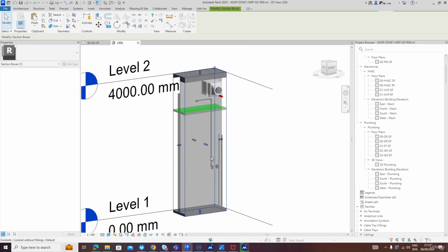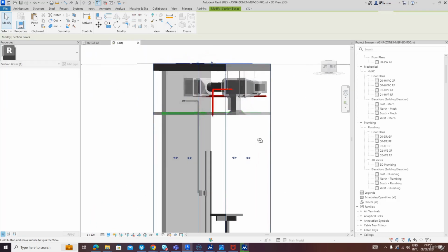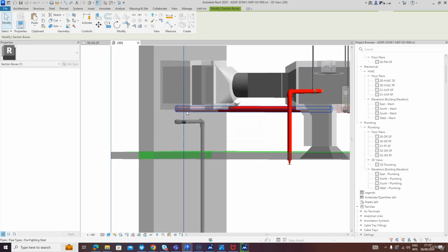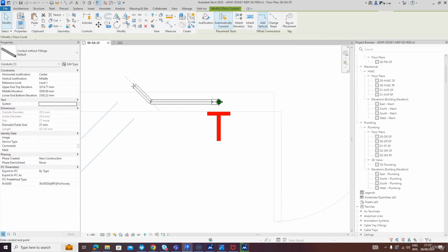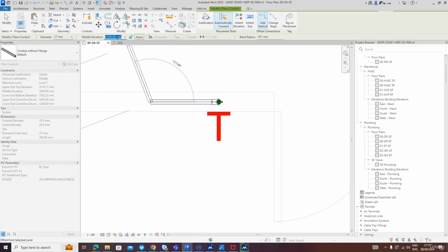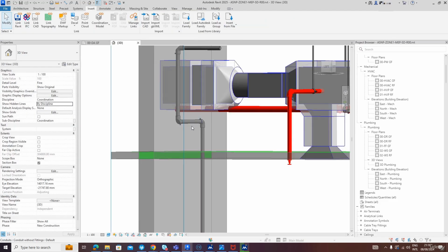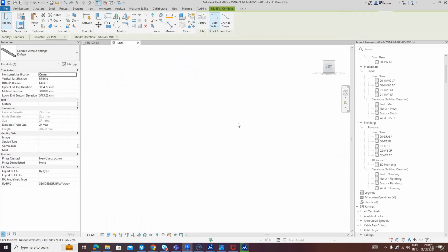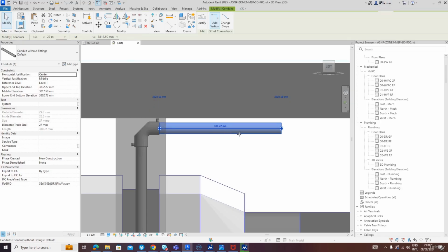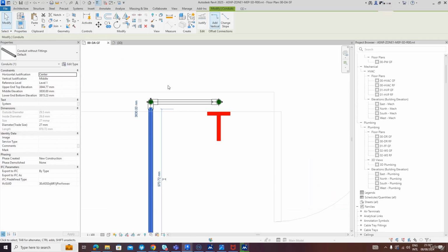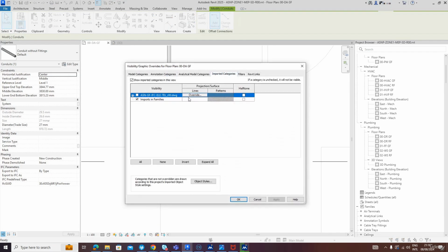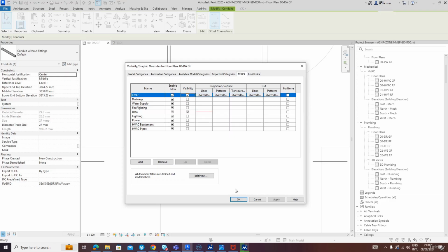As you can see, this is the conduit between the thermostat and the VAV box. Now we can move. I will move inside the wall, not like this. I will draw a conduit and I will move 3700. What is the height of the slab? 3800. And I will make it like this to place it on the slab level exactly above. I will use the keyboard arrows and I will drag it till we reach above the VAV box. Go to visibility graphics, import categories, to filters and HVAC filter.